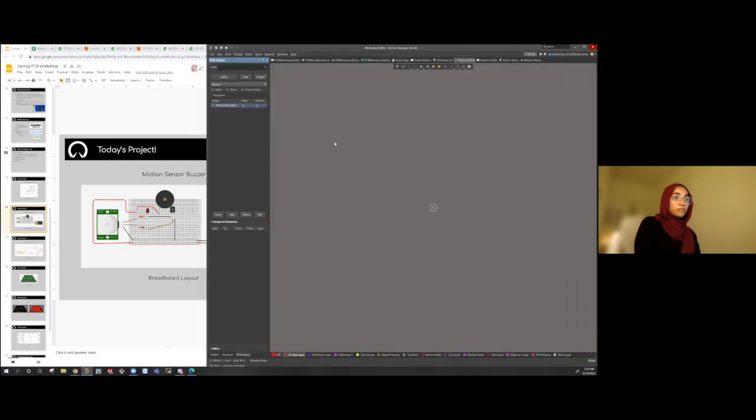So there are several ways to make a footprint, depending on which component you have, either SMDs or through hole. Obviously the way you make your footprints will vary. There are a couple wizards on Altium that allow you to make footprints pretty easily.